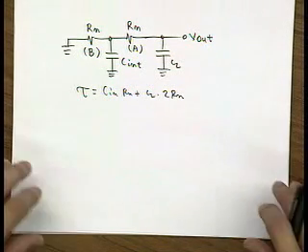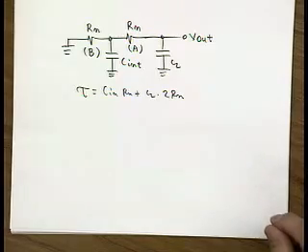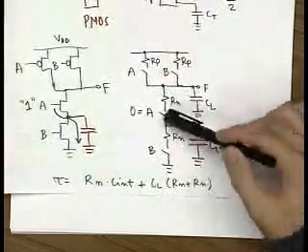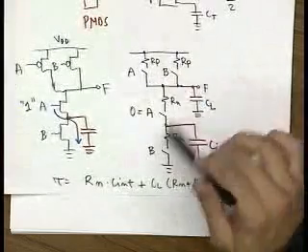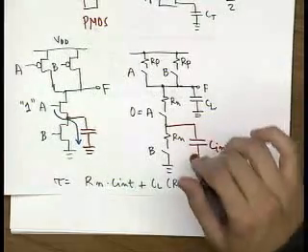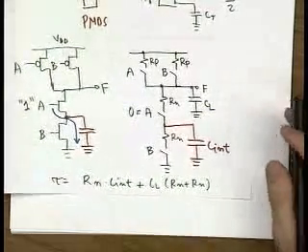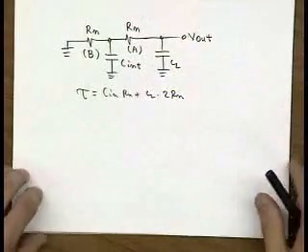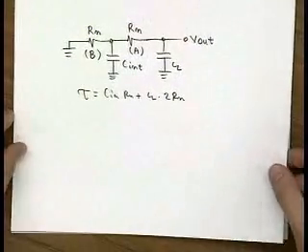Okay. So now let's take a moment to analyze what's going on with all these intrinsic capacitances and the propagation delay business for the NAND gate. Because if you understand the NAND gate, everything else will be in the same manner, and we can easily generalize to more complex gates.